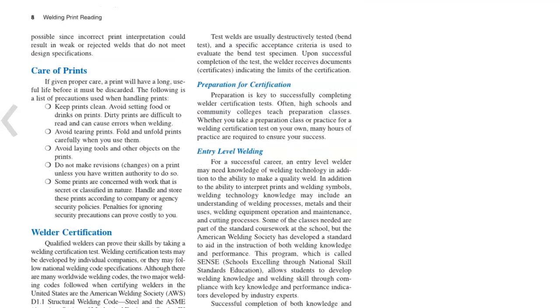Test welds are usually destructively tested or bent, and specific acceptance criteria is used to evaluate the bend test specimen. Upon successful completion of the test, the welder receives documentation or certifications indicating the limits of the certification. Preparation for certification. Preparation is key to successfully completing a welder certification test. Often high schools and community colleges teach preparation classes. Whether you take a preparation class or practice for a welder certification test on your own, many hours of practice are required to ensure your success.